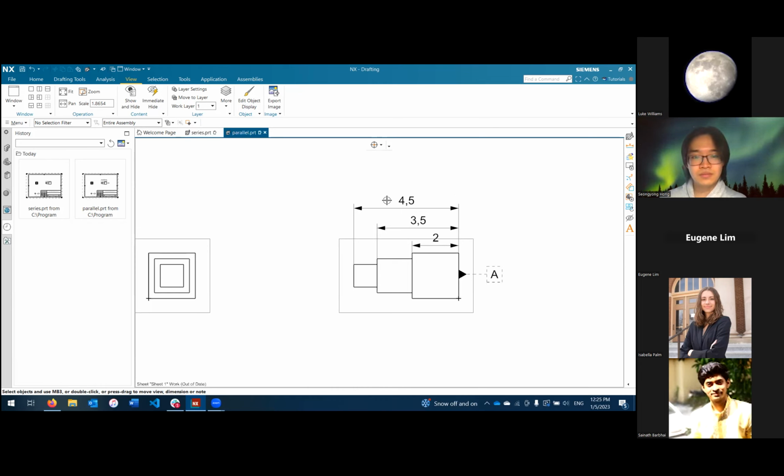So if we have a big chunk of aluminum and we're cutting it to make this part, and we're getting close to 4.5 as our overall dimension, the first tolerance that we're going to pass is going to be 4.6. That is going to determine when we essentially stop, because you can't really add material back after you've taken it off.